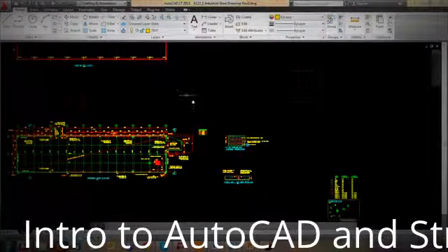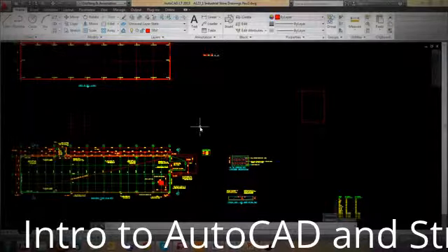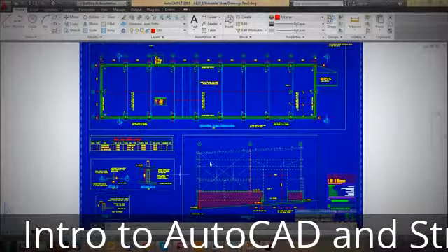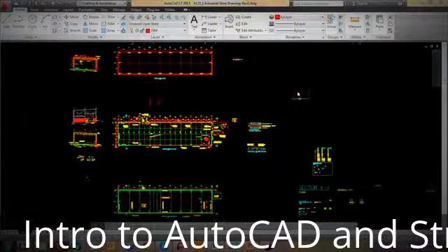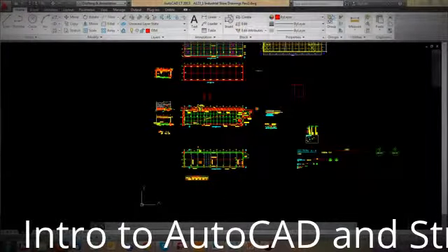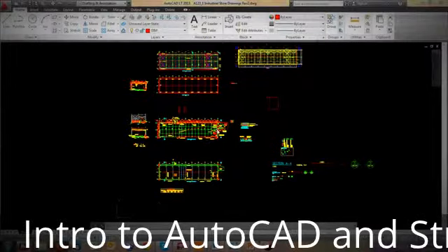You can, though, in model space, draw things at 1 in 100 next to a 1 in 1 next to a 1 in 50, and they will all come out looking as if you had produced it in paper space, but just be very careful of that. And then there are various other tools, annotation styles, etc. AutoCAD has a lot of new features with annotation styles, etc., and showing and hiding things, but we'll get to those. Well, a lot of those we won't use. We're just going to use the basics for now.